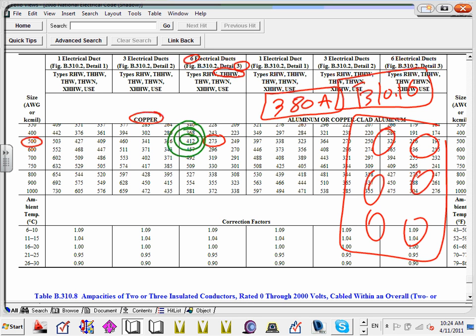Any question, guys? So, Spencer, my friend, if you use 380, and you want to write it down, just say that after we energize the system, it's highly unlikely that all the conductors are going to be carrying 4,000 amp. Why? Because of the diversity of the load, guys. We design a 4,000 amp switchgear, DJ, my friend, and when you energize and measure the amps, you find 1,600 amps, or 2,000 amps, or 2,500 amps on it. And it's designed for 4,000 amps.